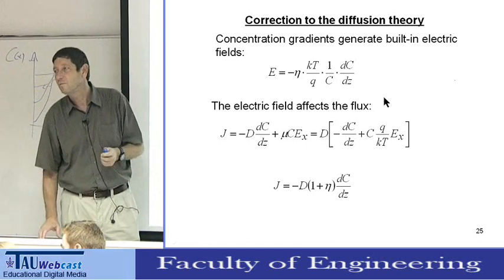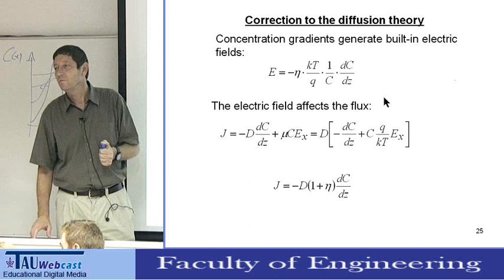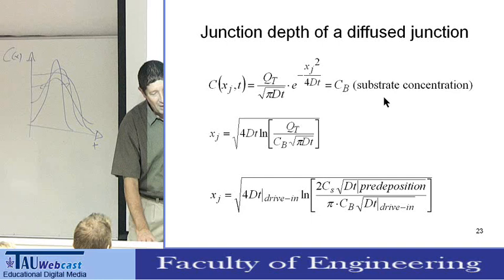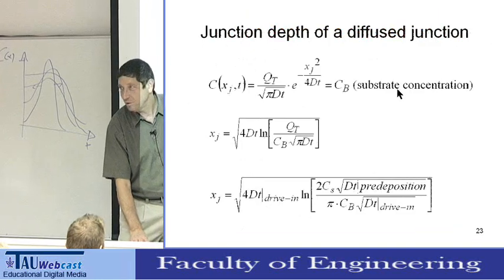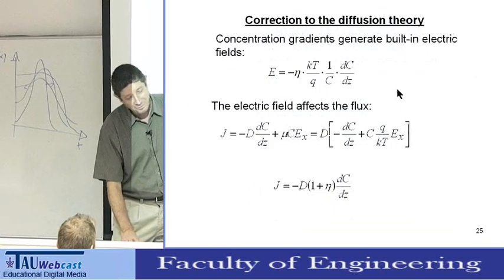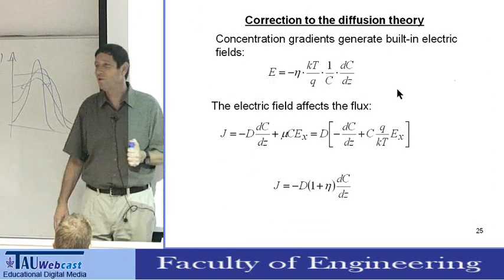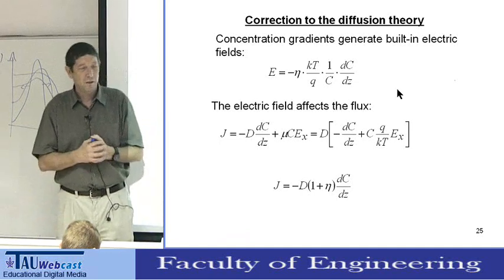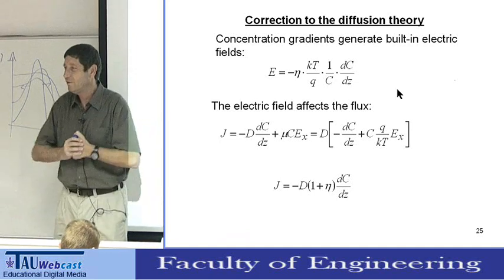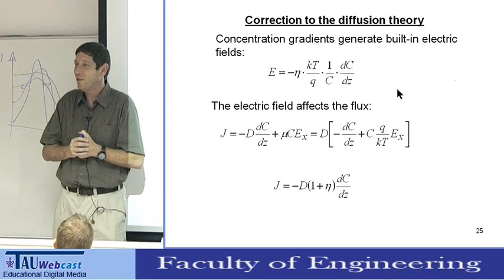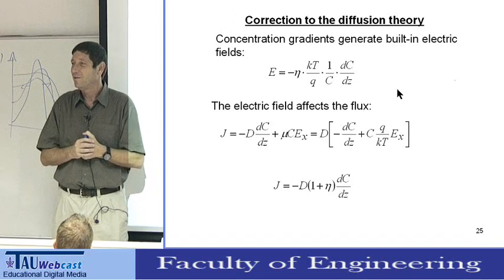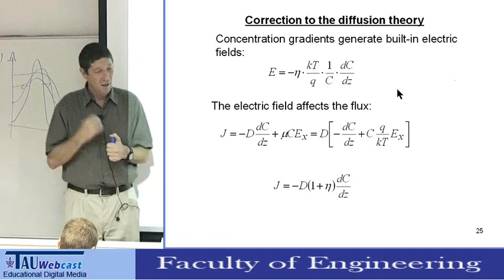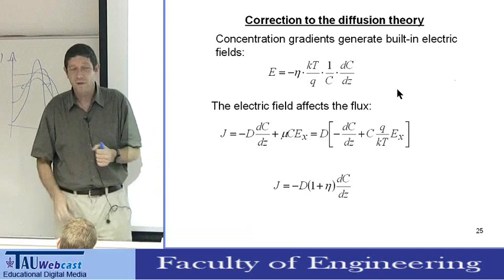Physical justification for a pure Gaussian function for the diffusion? This is why you get a Gaussian function here and an error function. These are the generating functions for the diffusion equation. I said the eigenfunctions of the diffusion equation are Gaussians and their integrals, so these are the natural solutions. Now, you have other effects in the semiconductor.